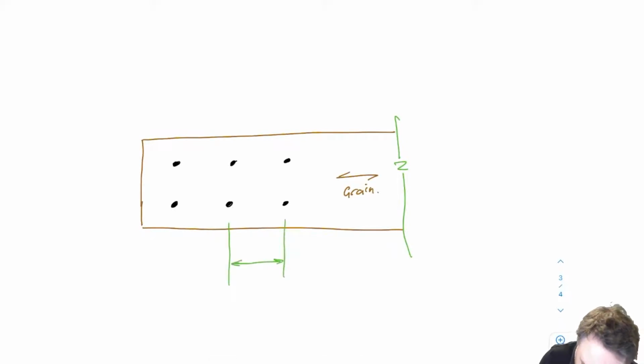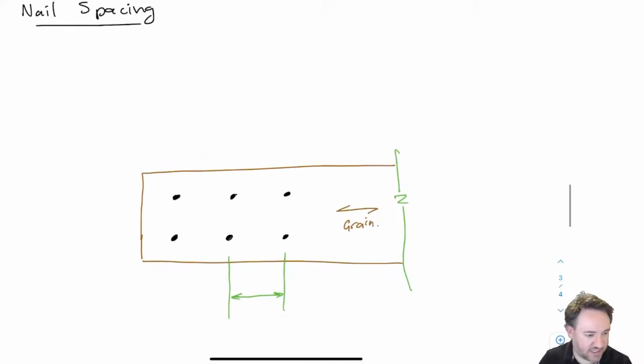One tricky thing between 08614 and 08619 is that in 08619 they have changed the names for all of these spacing parameters. Definitely for the better, but it's a bit confusing if you're going between the two. I'm going to put both. In general, that shouldn't be much of a problem, except that there are two things called A, and they're different things. So pay attention. If you go to your standard when you're designing and you look at the value that's there, and you're only dealing with one set of values, it should be easy enough. But I'm putting both to future-proof this a little bit.